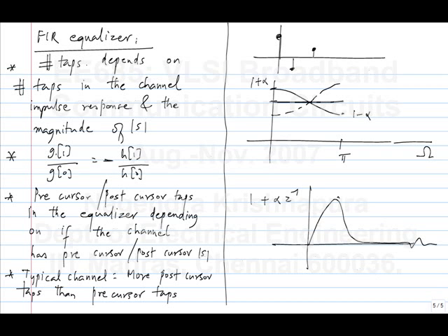But because the ISI is because of band limiting, the reason for intersymbol interference in our case is band limiting. Because of that, the pulse tends to broaden. So you'll almost always have the first precursor and the first postcursor to be the same sign as the cursor. That is positive. So that means that in the equalizer, the corresponding taps will be negative.